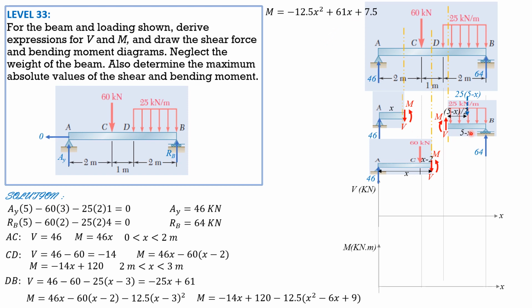Now, if we consider the simpler free body diagram, which is this, the moment equation is clockwise moment equals counterclockwise moment. So moment, therefore, in section dB is 64 times 5 minus x. So that's the applicability.